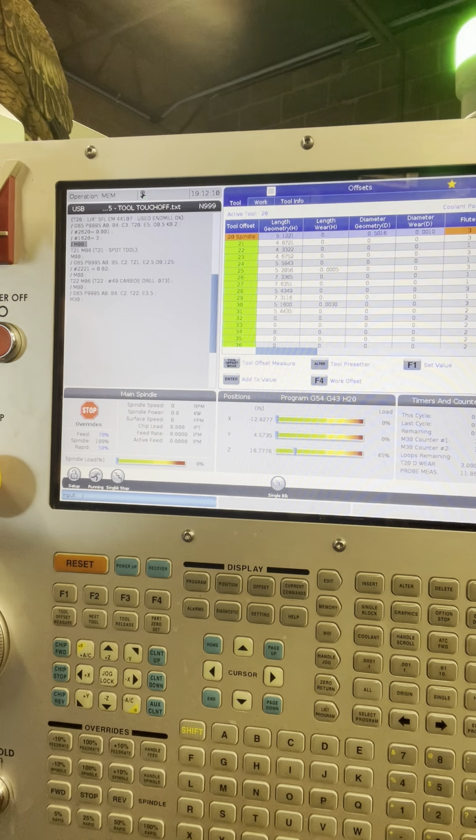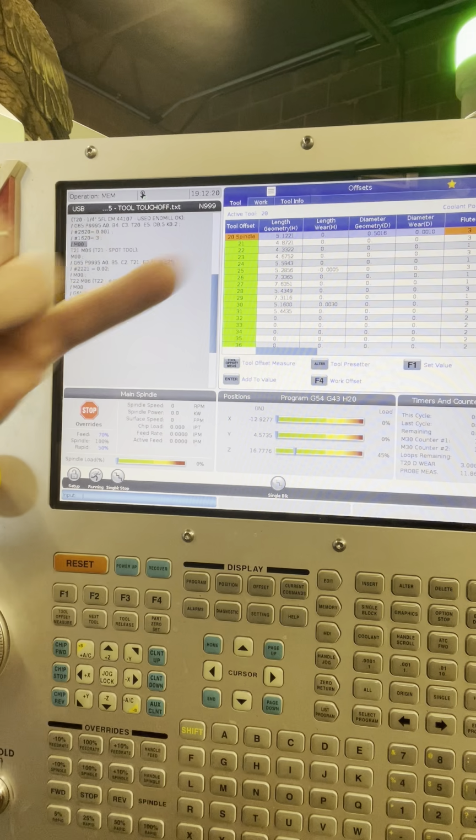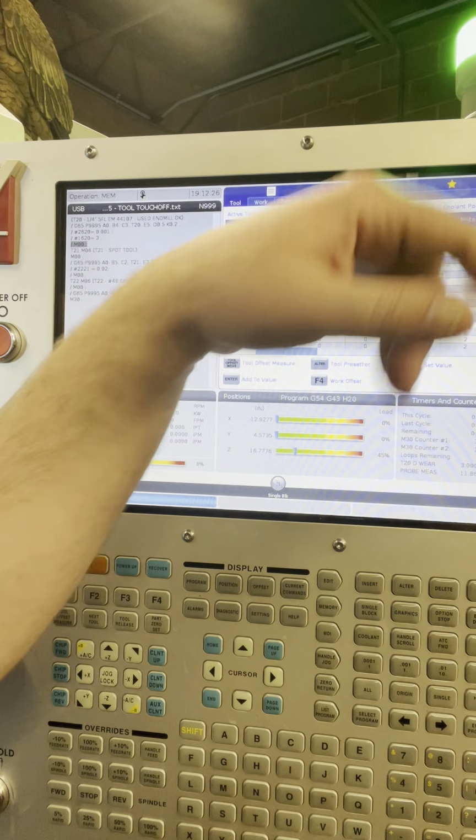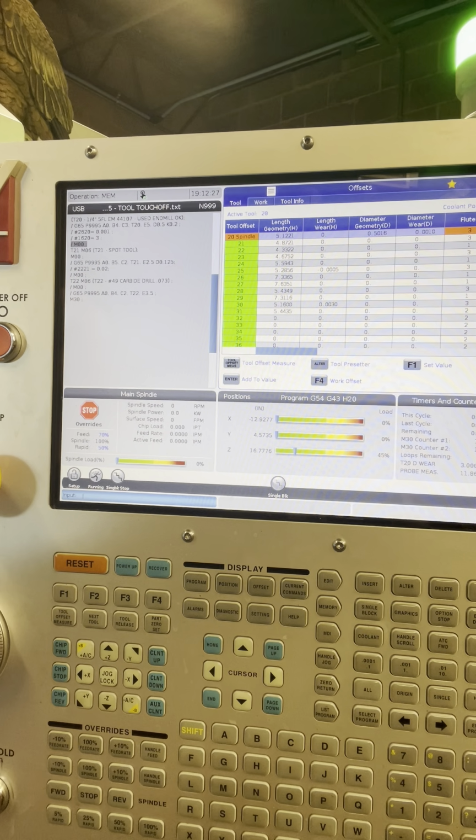So now if Brett's going to use this, he can save all this data because he's going to use that same tool. He's going to put the tool number in here and everything. So he knows it's a 3 flute tool. So he won't have to add that next time or change it. Maybe it says 4 or 5 from something else and didn't get cleared out. Do they all go to 1 when you origin? I've never origin. All right, I'm going to origin.